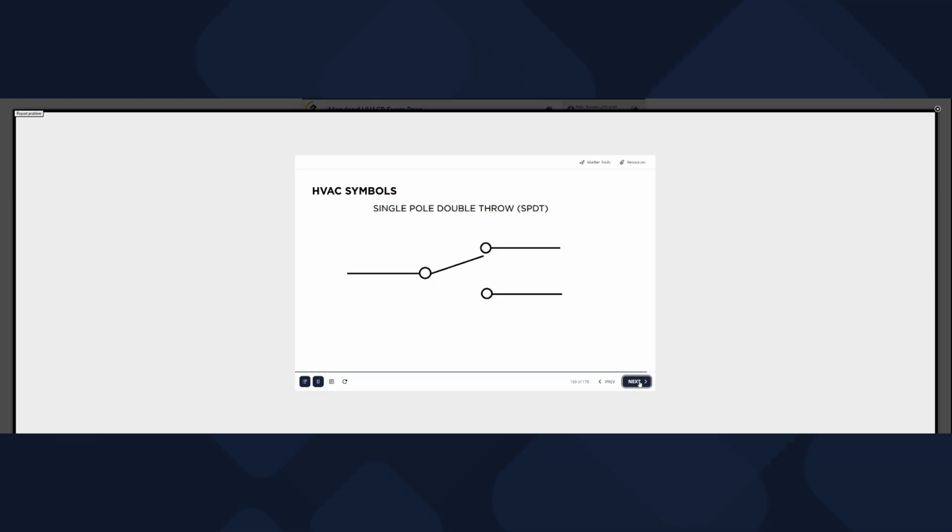This is the symbol for a single-pole double-throw switch, also known as a two-way switch. A two-way changeover switch directs the flow of current to one of two routes according to its position. Some SPDT switches have a central off position and are described as on-off-on.